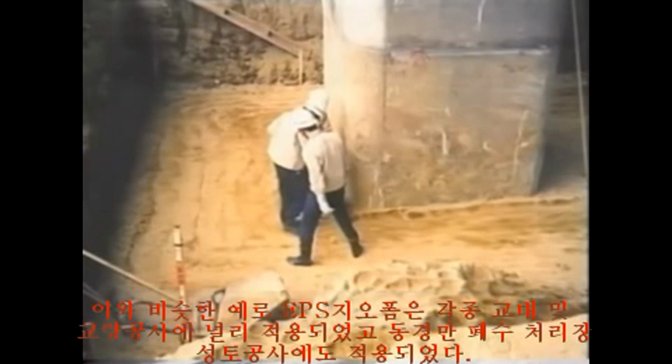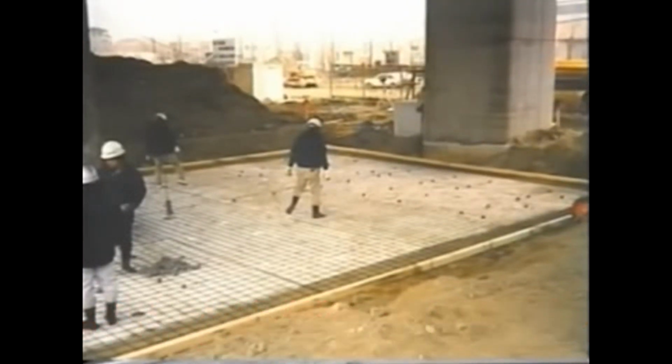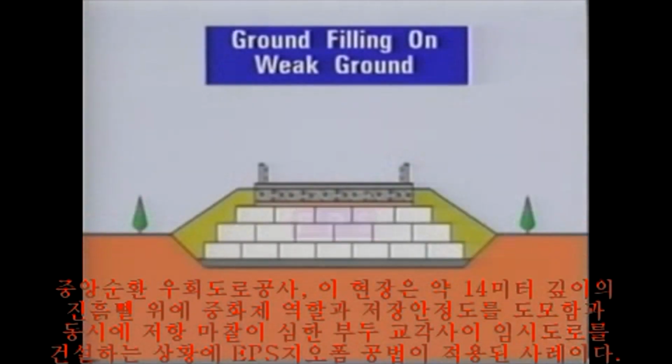At this location, the EPS construction method is employed to counteract the concerns regarding settlement due to ground consolidation from the accumulation of about 40 feet of alluvial clay. Also, since temporary roads are positioned between bridge piers, there is a danger of negative friction developing at the base pilings. Geofoam is utilized to counteract and reduce this problem.